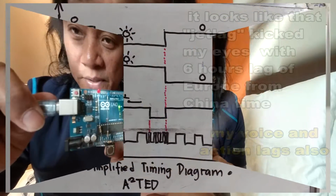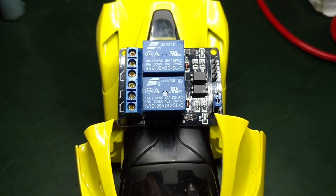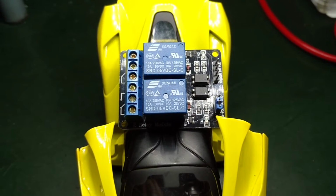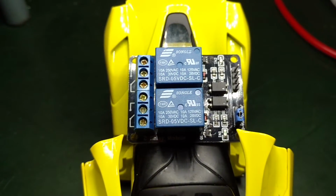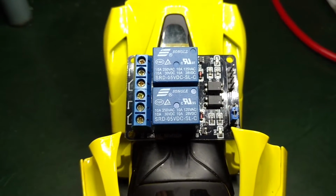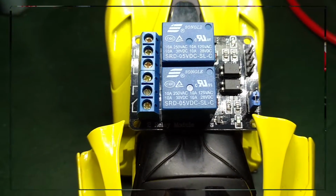There you are. What I'm going to do here is replace those two LEDs, the red and the blue LEDs, with this 2-channel relay board. Here is the relay that I can find in the local market. From the marking on the relay body, it says 05 VDC. That means its operating voltage is plus 5 volts. Bingo, because the Arduino operating voltage is plus 5 volts.